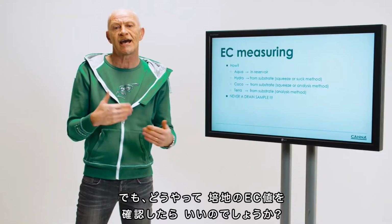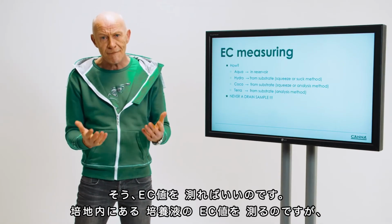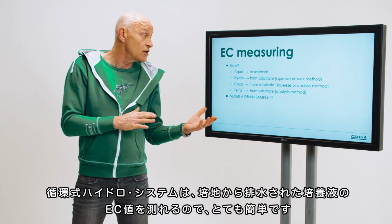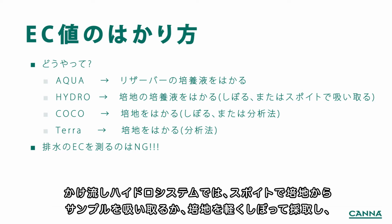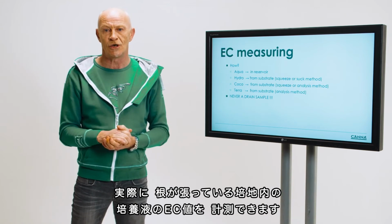But how do I know that I have a problem with the EC in the substrate? Well, you can measure it. You can measure the solution from the substrate. In a recirculating system, it's quite easy. In the reservoir, you see that the EC will rise just by taking a sample and you know the number. For a run-to-waste system, often you can suck water out of the substrate, or sometimes even by squeezing a little bit, and directly you can measure the EC which is in the root zone.